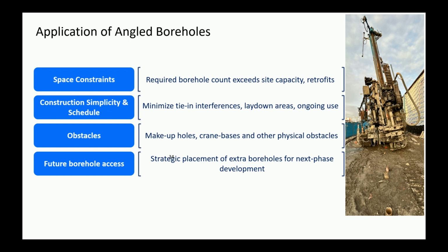We were able to drill these holes still because we were doing angle holes out under that future building being built, rather than trying to drill under that building or in parking lots beside it, which was an active police station still in service. So we didn't want to get mixed up with those guys. So we drilled off to the side, and on one side is Eglinton, which is a major city street running there with all sorts of stuff, and then the building off to the right. And that's the kind of application that we're seeing for angle holes quite often.